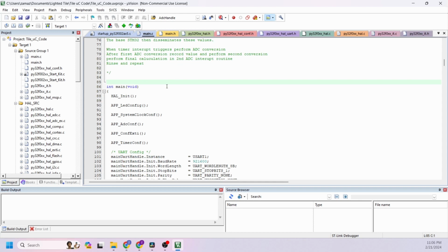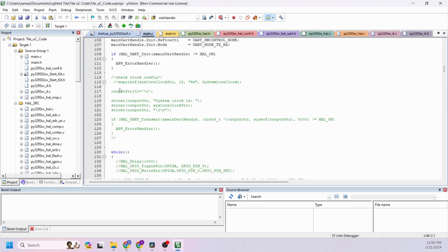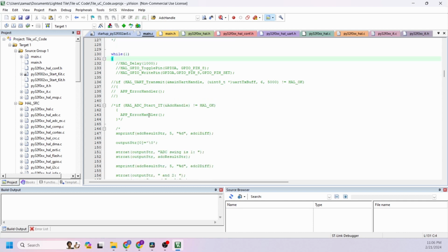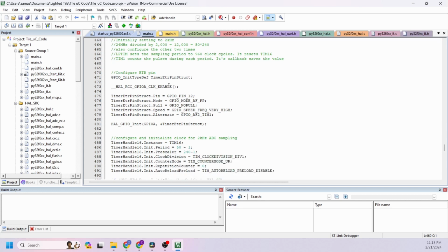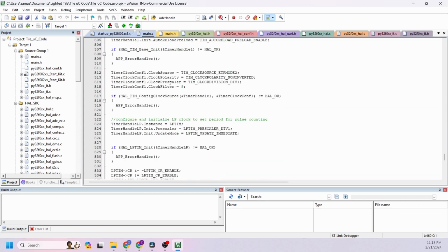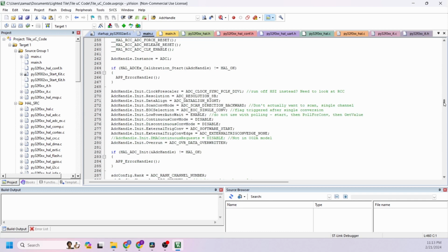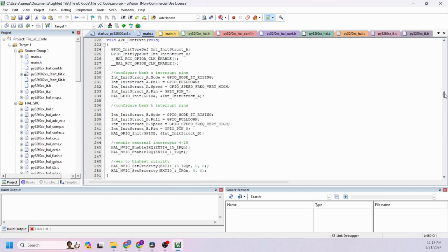I implemented this code in a timer and interrupt-based fashion. That is, in the while loop of the main function in the main.c file, there's absolutely no code. Just antiquated, commented out stuff that I'm afraid to delete in case I need it again. I might be a bit of a code hoarder. Instead of the main loop code, there are 2 timers implemented that periodically trigger events, and other functions. There's also an external interrupt implemented that triggers a specific piece of code when an external pin transitions. And that's pretty much it.